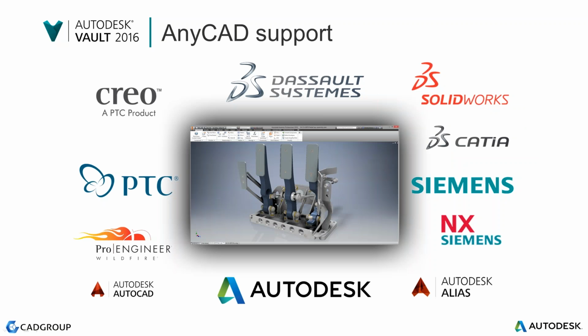Next thing along was the AnyCAD support. So in Inventor 2016, there is the support for AnyCAD. So in a nutshell, what that is, you can import native SolidWorks or Creo or PTC data straight into Inventor. Instead of having to convert it to a SAT file or a STEP file or an IGES file or whatever it may be, you can import the native, say, SolidWorks file directly, and if the SolidWorks file updates, your Inventor file will update. So Vault will accept the Inventor AnyCAD.